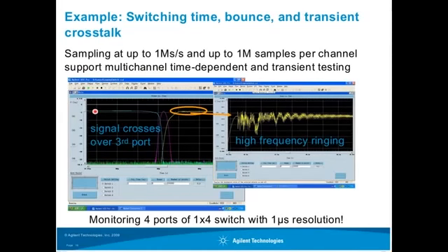Here what you can see is the signal is on the first channel, which is blue on this trace. It's probably a little hard to see at this resolution, I hope not too bad. At the time of the event, the light switches away from that port. This would be the fall time of that switch. It picks up in the new port where the signal is being sent. Interestingly, in this particular case, it crosses over one of the other ports, so there's a fairly brief transient signal on that port. And then finally, once we get into the new port, there's some ringing. This is now shown on a 1 microsecond time scale, and it decays pretty fast, but that was a ringing event that we could show using this kind of measurement. So that would be the switching time and the bounce that we would detect on that kind of device.